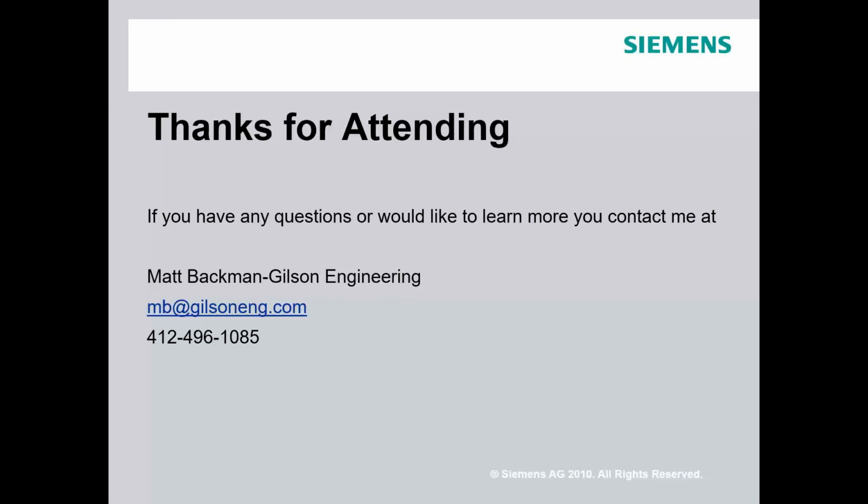PS100, yes, can be used outdoors. Right now, like I said, there are no area classifications at all until April. Right now, we're in the middle of all the FM, CSA, ATEX, CE, UL, whatever stuff, which is expensive and not fast. But yes, soon it will have that. Now, our flagship PS2 has all that stuff. So yes, you can use it outside. We're assuming 9 times out of 10 that the valves are outside. It'll be NEMA 4X as a minimum, and it'll be fine.